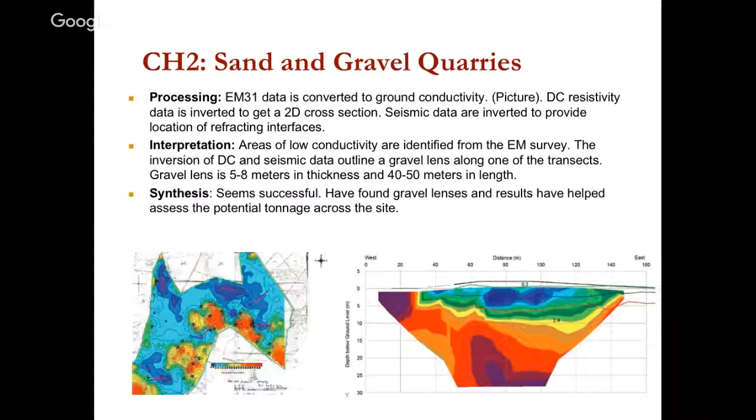So now you've got two geophysical surveys. They kind of provide information about where that sand and gravel deposit is, and they sort of confirm each other. So that would be a really good type of survey. These other lines that are on here, actually that was the results from the seismic survey. These numbers are indicative of seismic velocity in kilometers per second, and that's basically 300 meters per second up here, and it gets down to a couple of kilometers per second down here. So everything is kind of fitting together.